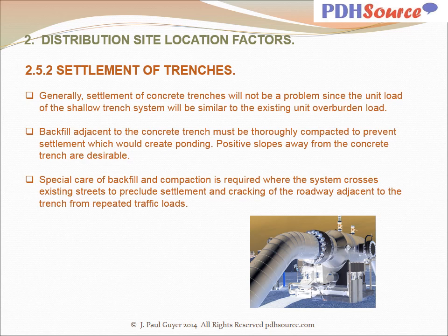Special care of backfill and compaction is required where the system crosses existing streets to preclude settlement and cracking of the roadway adjacent to the trench from repeated traffic loads.